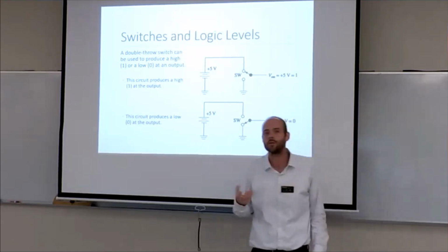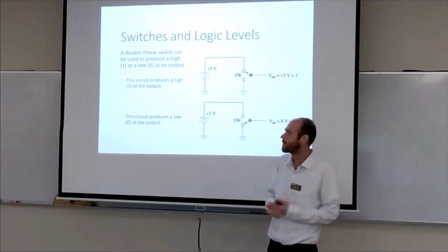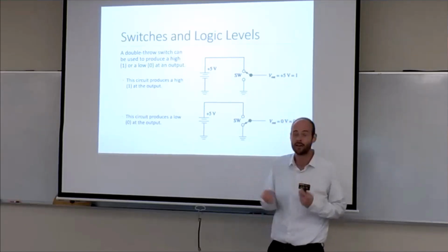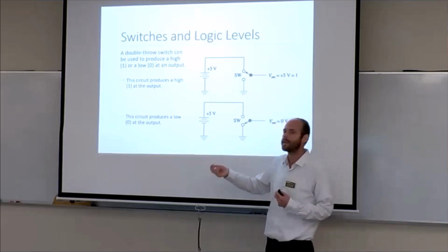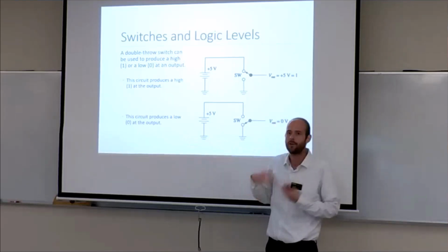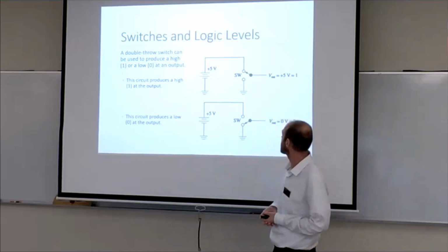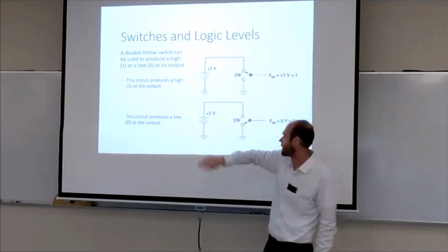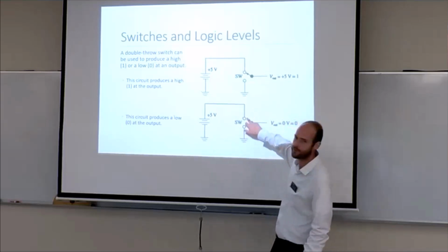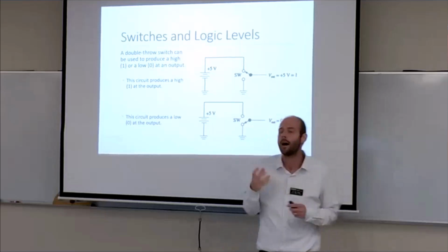Switches can be used to create voltage level logic, so a 0 volt or a 5 volt. We've seen this in our interaction with things like pull-up resistors and push buttons, so we can have a grounded input, maybe going to an input of our microcontroller, and then when we push the button, it goes in the opposite direction. And here you can see some switches being used for that purpose. We've got ground or 5 volt, just hard connections going to some output.